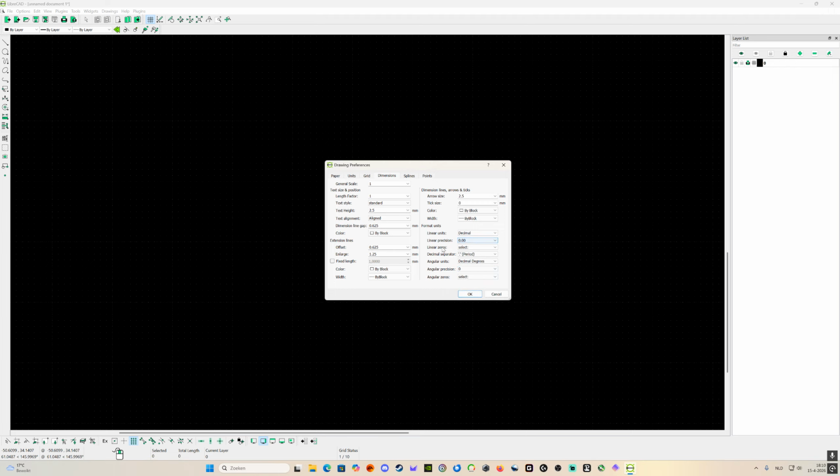That means that if I later make my measurement lines, I get 2 numbers behind the dot. The angular position is only the angle, but if you want more precision, it's possible. So that's okay. My paper sizes and my drawing sizes are correct.